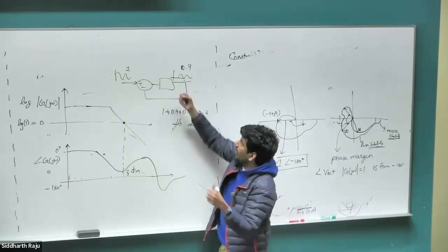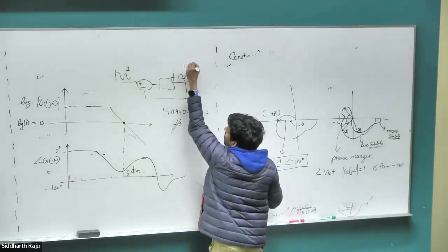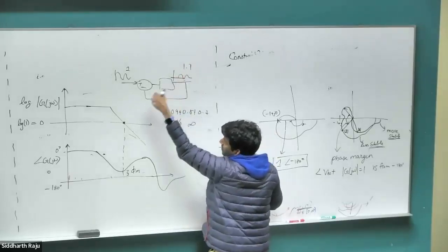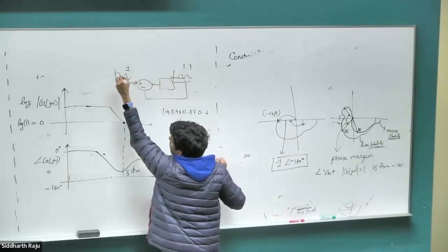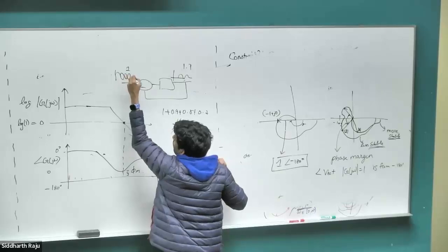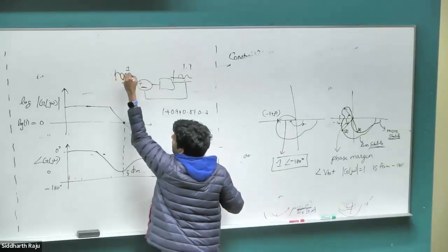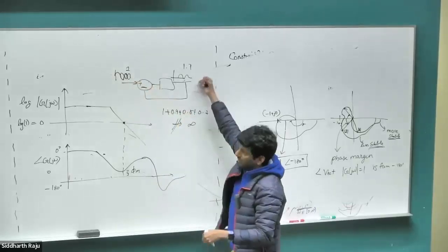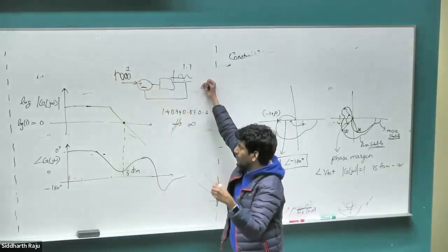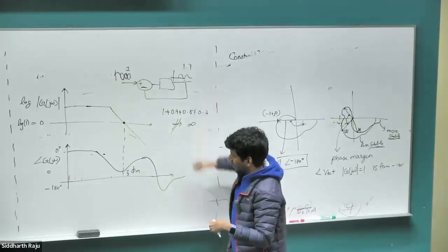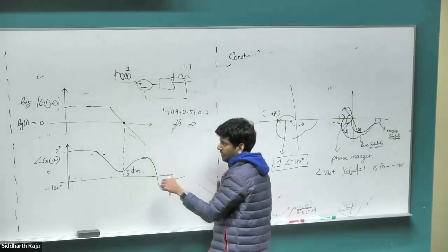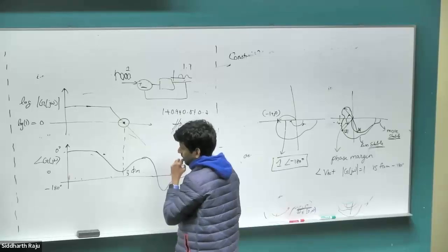Right? So if you had 1.1 instead of 1. So whatever the signal is, if it had a phase shift of 0 degrees, versus a phase shift of 180 degrees, this is what the signal would have looked like if you didn't have this negative. But since you are putting a negative, this ends up aligning with itself, keeps on adding. If you have a signal greater than magnitude 1, then it adds more and more, faster, and becomes more and more unstable. Right? So anything happening afterwards is fine. It is only the point here that matters.